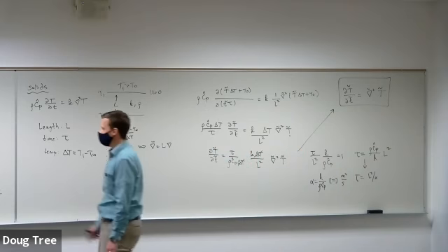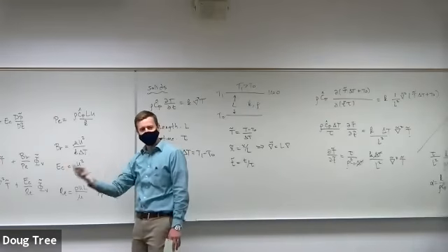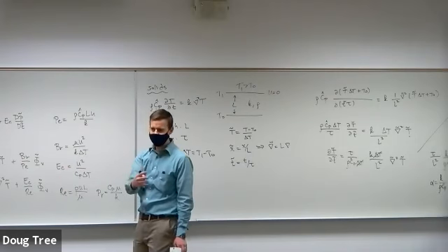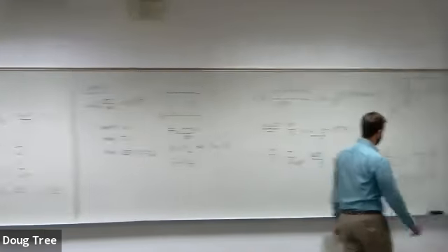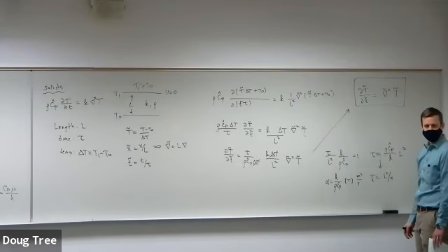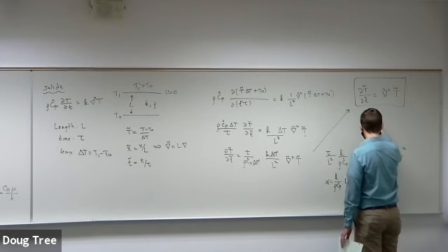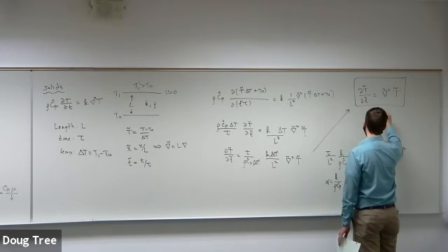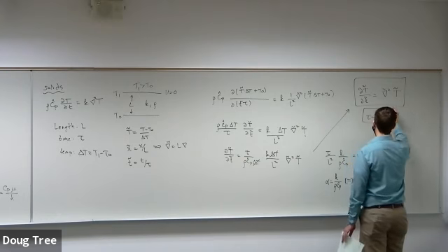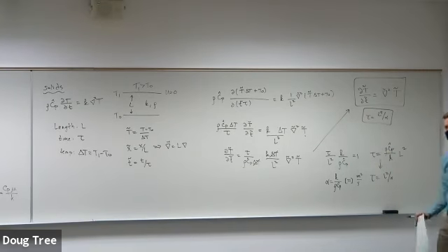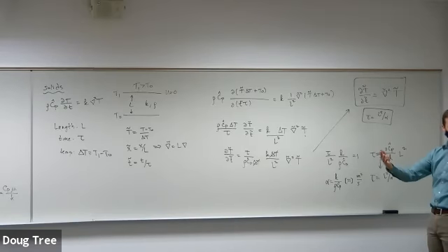So in the Peclet number over here, I had to take into account conduction and convection. I had a time scale from convection and I had conduction. But here I only have a time scale from conduction. Okay, so I get tau is equal to L squared over alpha. And this idea that there's a characteristic time scale of diffusion is going to be really important for us in the future of this class. I think it's one of the most useful things I ever learned in transport, so I wanted to highlight this here.